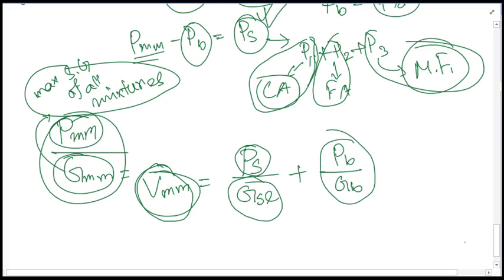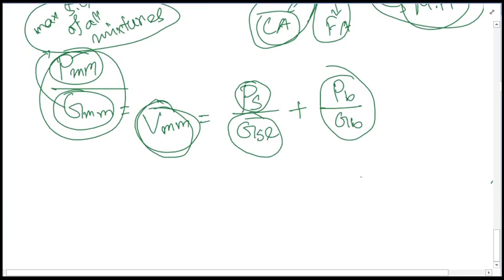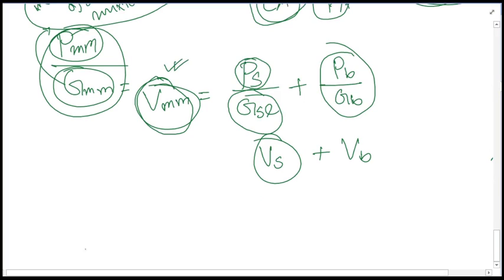So in terms of volume, this is the volume of bitumen, and this one is equivalent to the volume of all other aggregates, so VS. So from this you can easily understand that. While taking the total volume, if we deduct the bitumen, it is not necessary whether this bitumen is absorbed by the aggregate, or it is within the void space of combined aggregates, it doesn't matter.